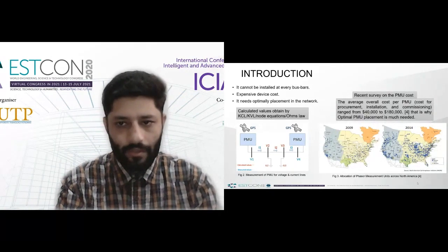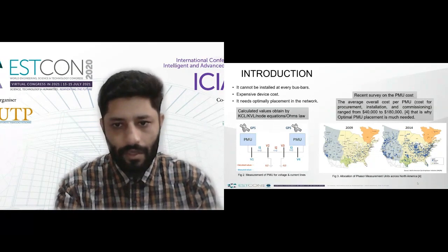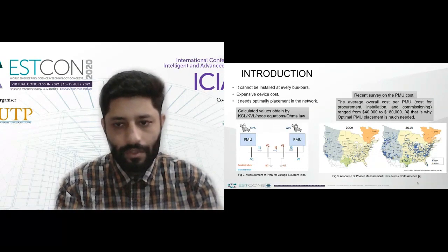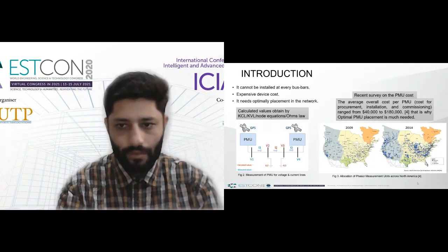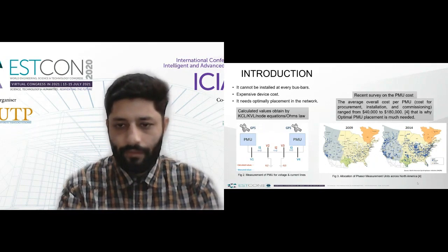A recent survey on the PMU cost shows that the average overall cost per PMU, including procurement, installation and commissioning, ranges from 40,000 US dollars to 180,000 US dollars. As we can see, the cost is very expensive and it is not affordable to install a PMU at every bus bar in a grid station. Therefore, optimal placement of PMUs is much needed in the electrical system.